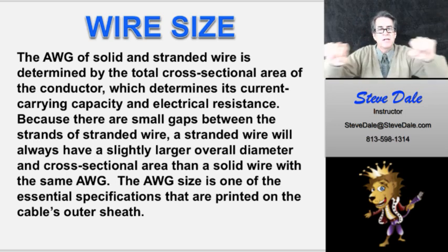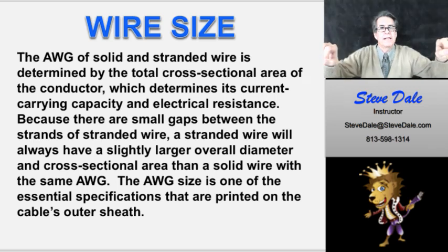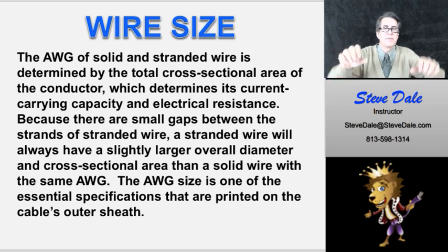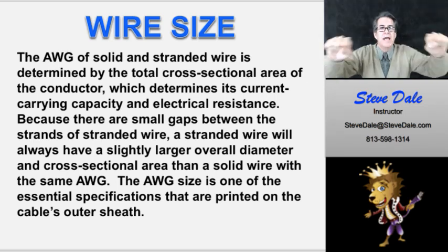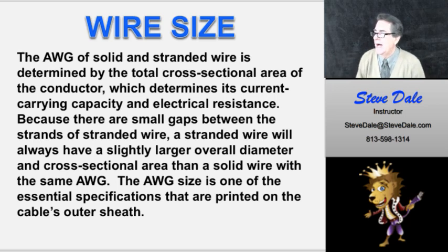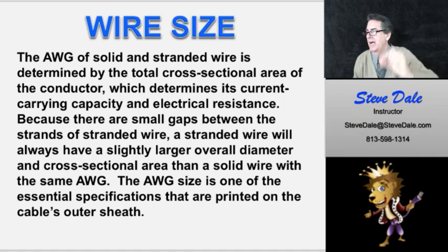So they heat it up and they stretch it and they pull it through a die, and each time they draw it, each time they stretch it, is one draw. And that's where they've got all these numbers from. So basically, if it's a 4/0, it's been stretched 4 times. If it's a 26/0, it's been stretched 26 times. Okay, so that's why the higher the number, the smaller the diameter size.